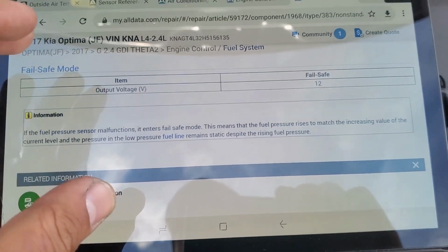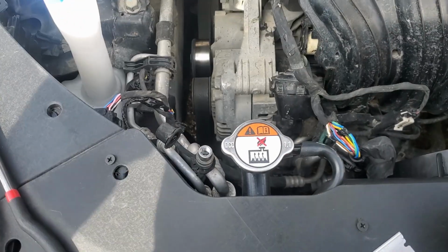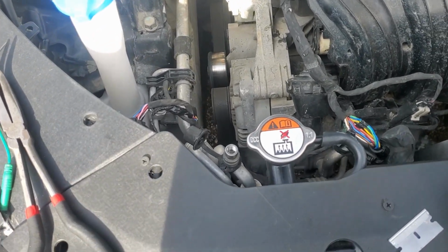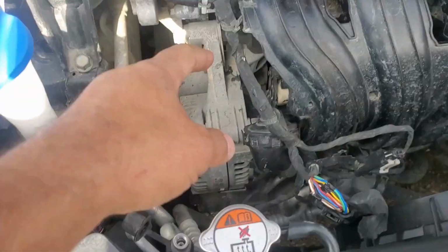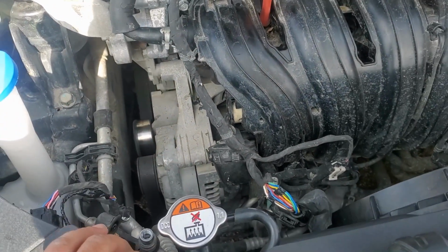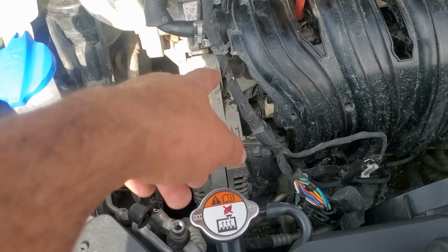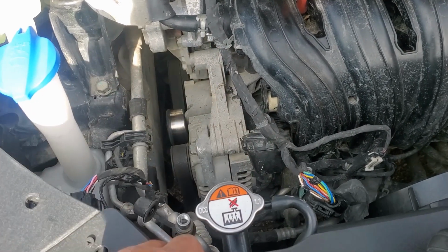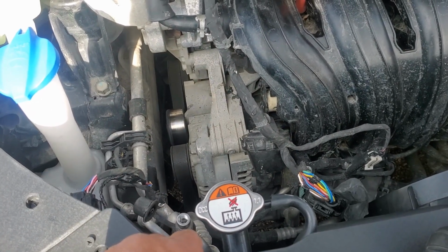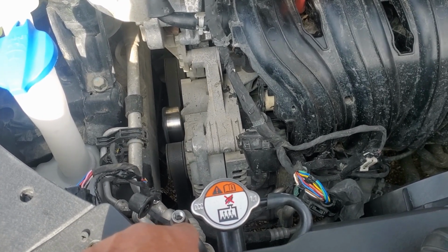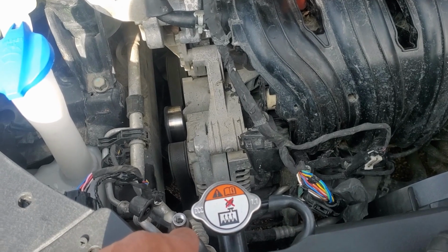The reason I'm focused on this, and not the AC refrigerant pressure sensor, is that on that one the signal, the middle one, we had 5 volts, plugged or unplugged.